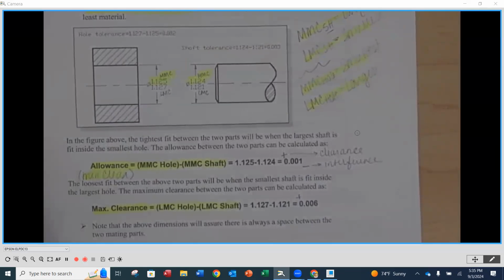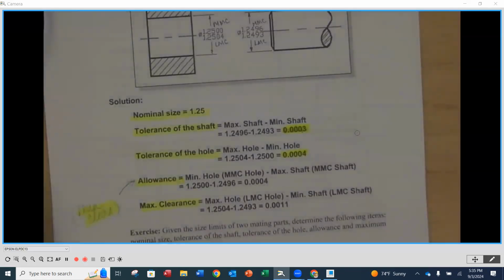It goes up, right? And it goes up really quickly, especially when we start having to get into reaming and broaching and grinding to try to achieve these things. And guess who's in control of the amount of tolerance that's on something? Yeah, point back at yourself. You as the designer, you as the engineer on that product, you are responsible for it. I'm going to say it over and over again, it's one of the biggest responsibilities in a company because it drives the cost of that product.